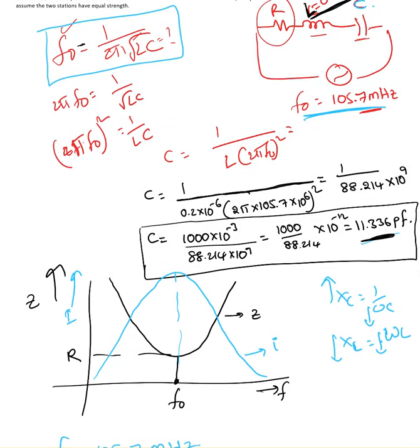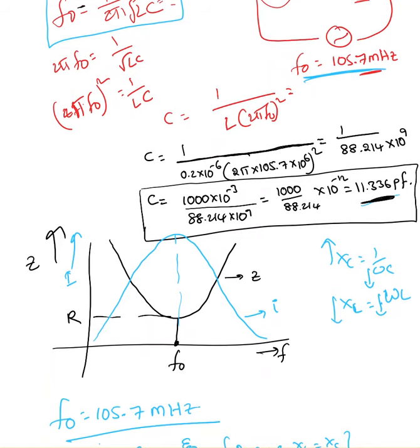And to reiterate, at the resonant frequency the circuit is going to have only resistance, because at lower frequencies, on this side here, XC is higher because omega is lower and XL is lower, so you will have R minus jXC, with magnitude square root of R squared plus X squared, so you will end up having more impedance there. And when you increase the frequency, omega L goes up, so that's another reason you will have more impedance there.